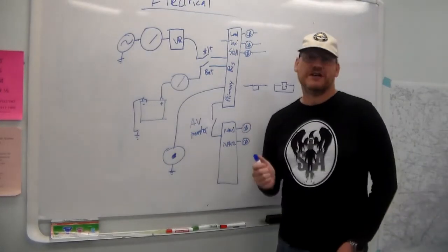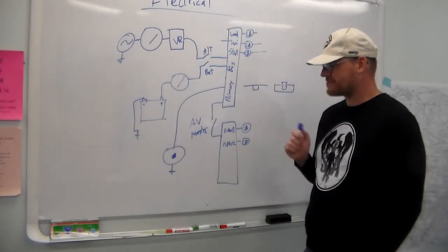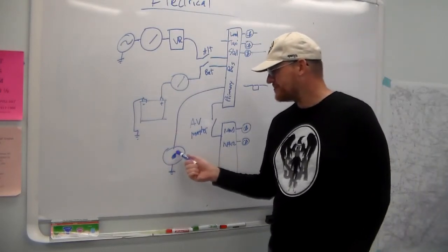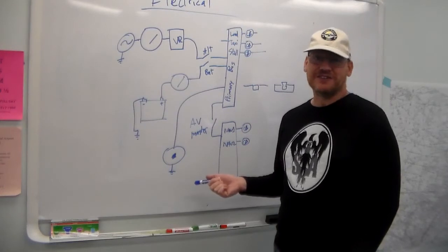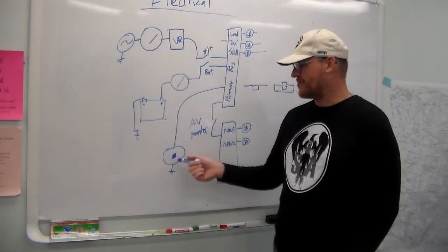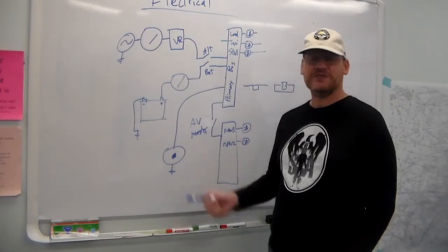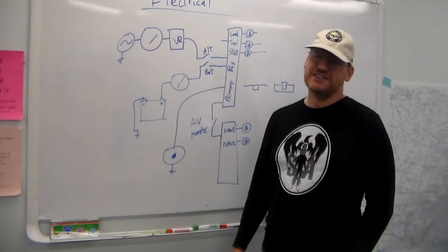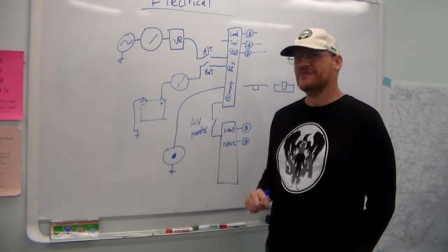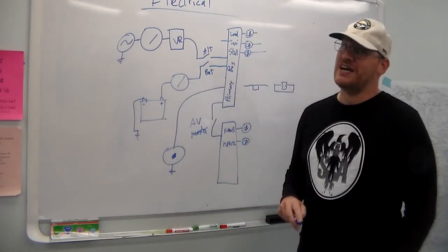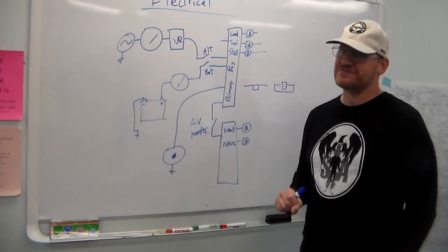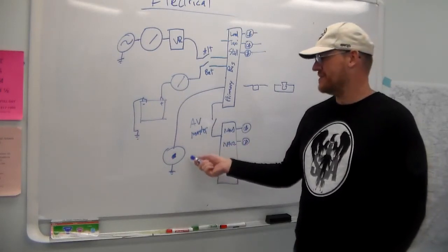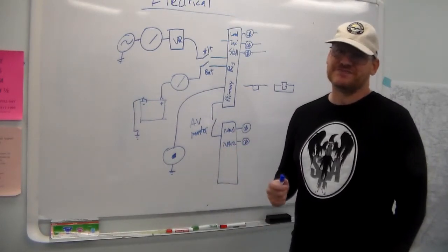All right, last thing I want to talk about with electrical systems. Many aircraft will have a ground power plug. So if you have a Piper, or basically most things that aren't a Cessna, it'll look like this. It's a round connection, it has a little post in the middle, and you plug a cable in and you can get ground power to start your aircraft. Which, again, if your battery's completely dead, it's not recommended you go fly with a completely dead battery. It's better to charge the battery and then go fly.